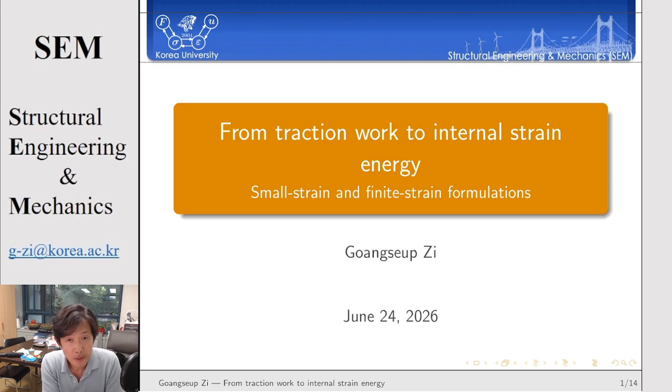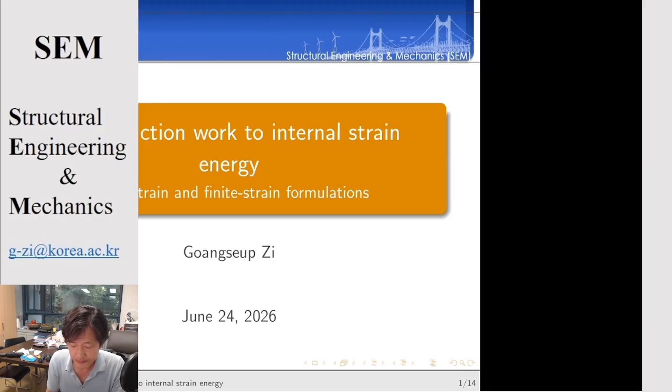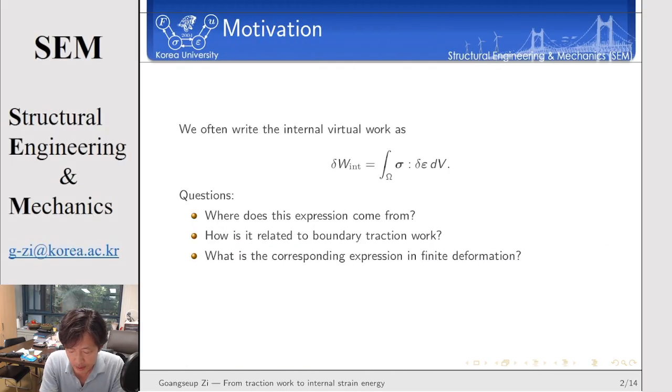In the last video, I showed you how we obtain the concept of stress tensor from the traction, the Cauchy approach using a tetrahedron. Today, I'd like to extend that consideration to obtain the concept of internal energy and the strain tensor. The motivation is given here.